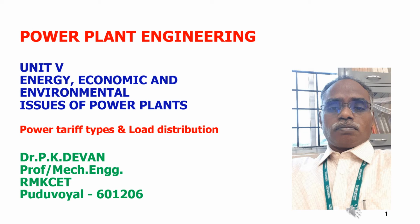Good morning, friends. In this video, we are going to discuss various power tariff types and different curves related to load distribution and economics of a power plant, whether it is a thermal power plant. Mostly, we are concentrating on thermal power plants, since 70% of the power we are deriving is from thermal power plants, that is, coal-based power plants. So, we will discuss in detail various types of power tariff, load distribution methodology, and how we are calculating the cost.